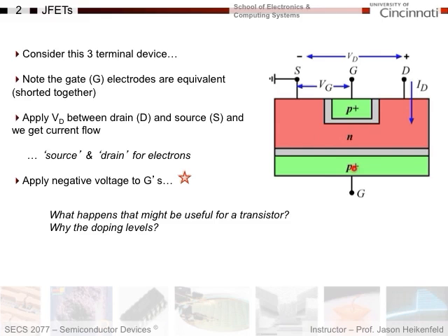Well, again, it comes back to that depletion. I want the depletion to occur only where it's going to do something for me, right? And the only place where this is going to do something for me is to deplete into this channel here, into this N-type channel. And so this is lightly doped, this is heavily doped. All the depletion will occur where I want it, which is into the N-type channel, and the device works as I would hope it would.